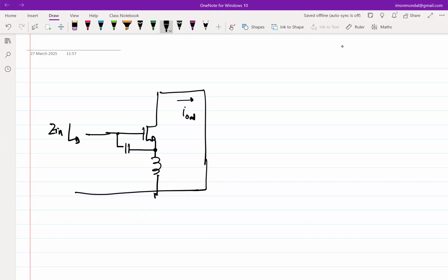Then we saw that if you have negative feedback or any sort of feedback or any sort of phase lag between two nodes, and you put a capacitor or for that matter even an inductor, then depending upon the type of phase lag, it is possible to get a real positive impedance looking into any node, and it need not necessarily be for this particular architecture. It can be for any other architecture. But the key thing is to note that whenever you put a capacitor or an inductor, you have to ensure that the phase lag still exists, right? Otherwise, you are not going to get any difference.